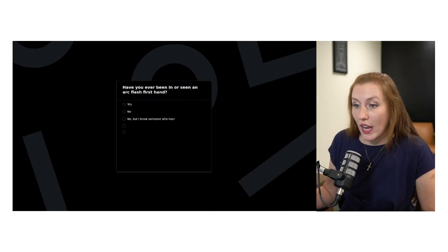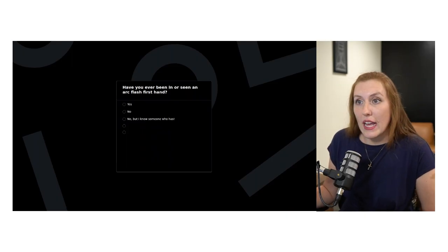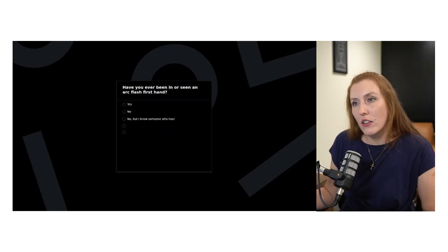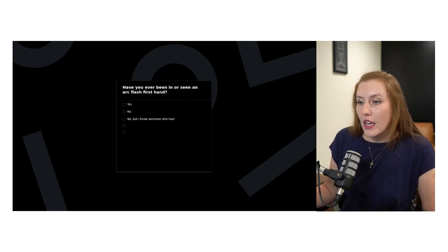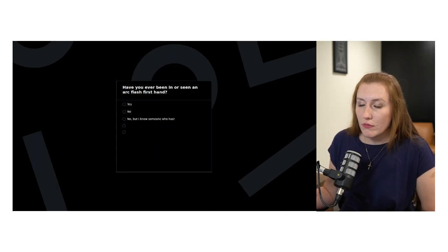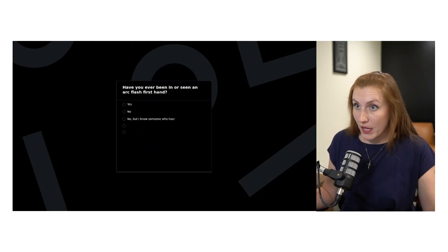If nothing has changed, do you still need to update the arc flash study every 5 years? The simple answer is yes. You have to have your arc flash study at least reviewed for accuracy at intervals not to exceed 5 years. If nothing has changed, great. You had your review. You don't have to necessarily change the labels out. However, that is something that we need to look at with this new NEC version verbiage.